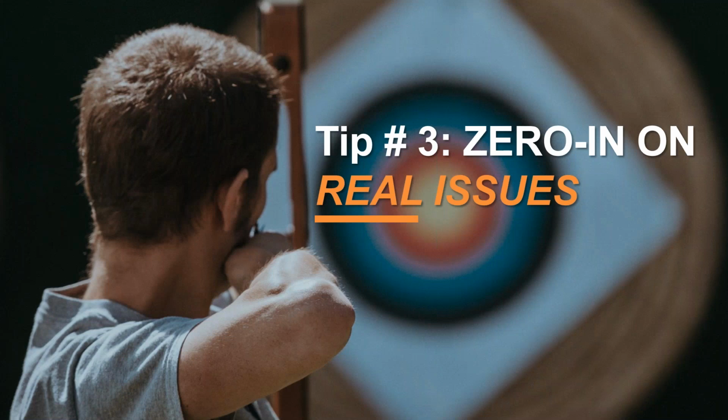So our final tip, number 3, is effective root cause analysis. So zeroing in on the issues. We must see the problem before we can find a solution. So we had an example where the production manager identified that short stops was a major cause of lost production on the machine. On investigation, the conveyor line person informed the production manager that during a single pass of product A, the line stops. So he opened up the safety screen, realigned the product that catches the machine door, closed the safety screen and the conveyor belt starts up again. For every 2 seconds of real production, that issue caused a stoppage of 4 seconds of downtime.